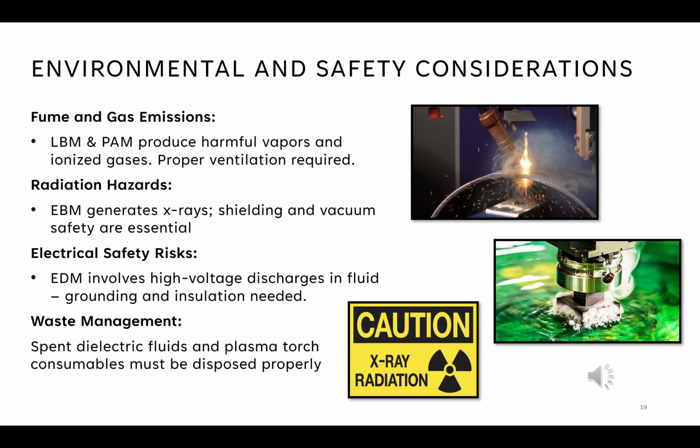While thermomachining is extremely useful, it comes with serious environmental and safety considerations. For instance, laser and plasma processes emit harmful fumes and gases, so proper extraction systems are necessary. Electron beam machining must be conducted in a vacuum chamber and produces X-rays, so shielding is critical. EDM uses high voltage and immersion in dielectric fluid, making electrical safety and proper grounding essential.